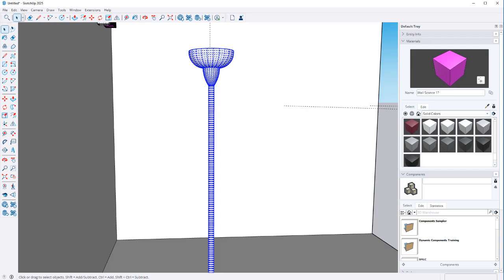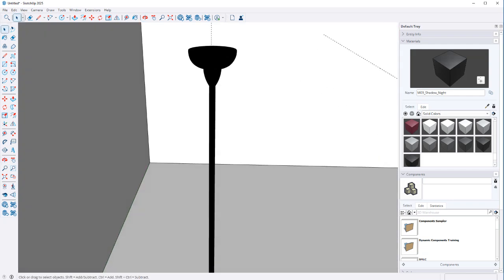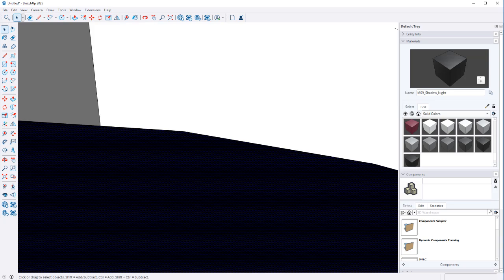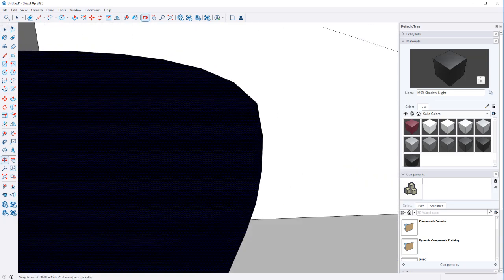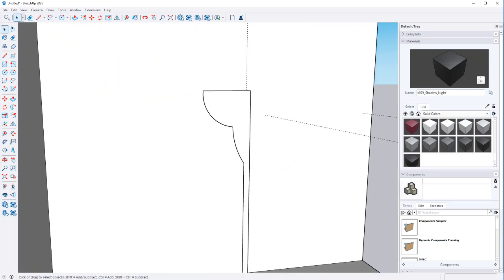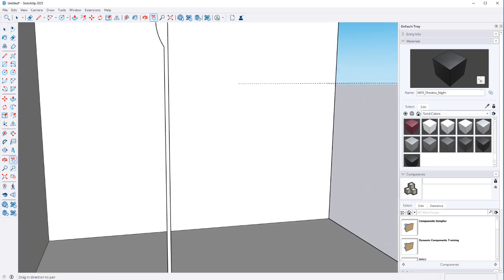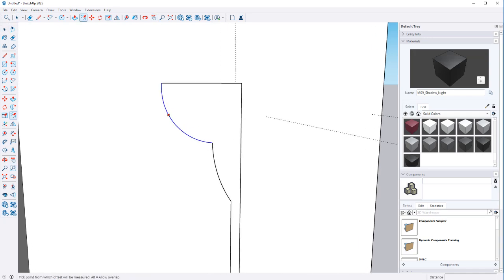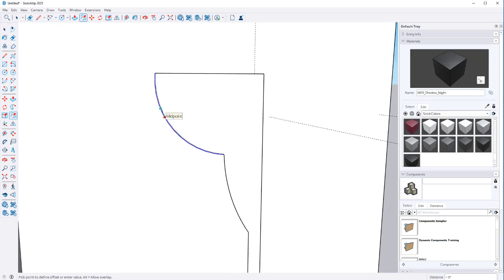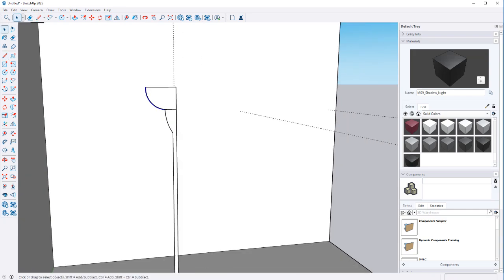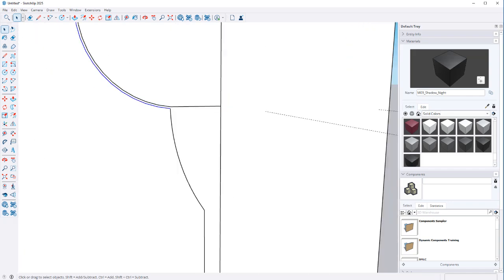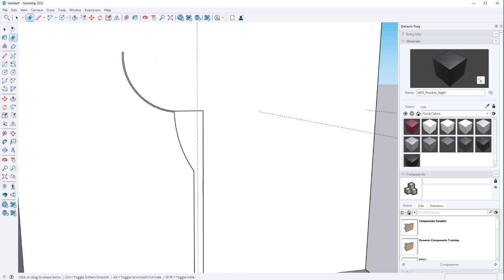With one of these, you're going to go with black for the main material, and then this bowl up at the top, you would go with, so this is a case where, oh, you know what I didn't do? I didn't give the bowl any thickness. So let's go in here, we'll offset this in just a tiny amount, like very thin. Some 3D programs will be able to actually take that and generate a translucent surface there with that material. So now we can get rid of that.